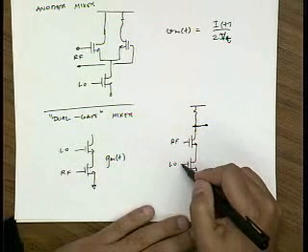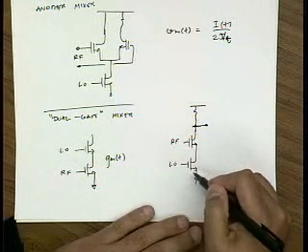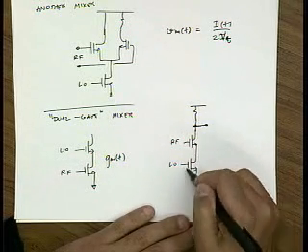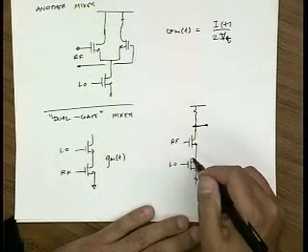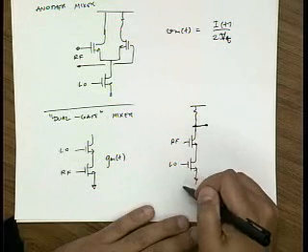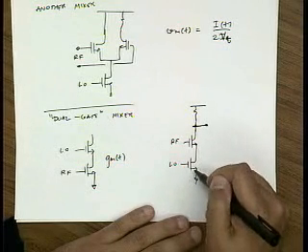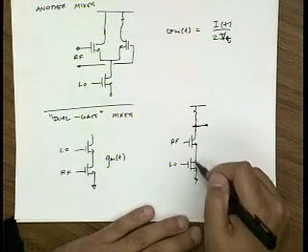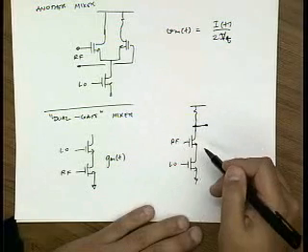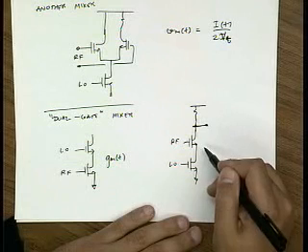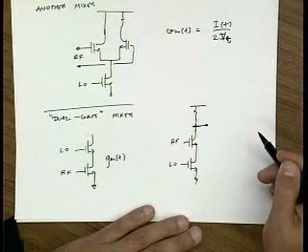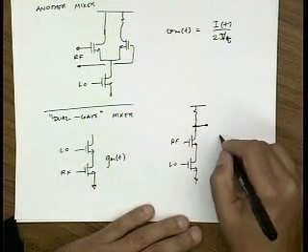And by changing the amount of LO, I do change the degeneration somewhat, right? But then I have to do something very drastic. So for instance, if I make my LO very negative, this transistor goes into cutoff, and then you present a certain amount of degeneration. You still have bad gain. When you turn this thing on, it turns into a current source, and you have another amount of degeneration. And so you still have bad gain. So this always has low gain.